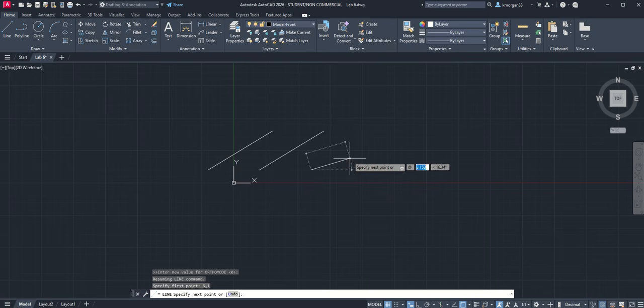So we put in the at mark and then 5, of course, and do the little less than sign on your keyboard, which looks like that, less than, and then 30 degrees, and then you enter and then escape. So now we have just drawn the third line, which is parallel to the next line. So that's 6, 1, and then of course 5 less than 30 is in there.